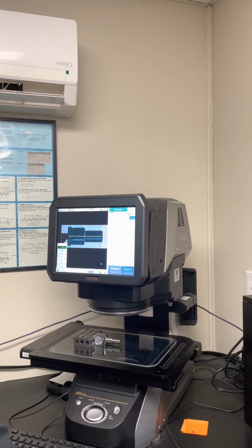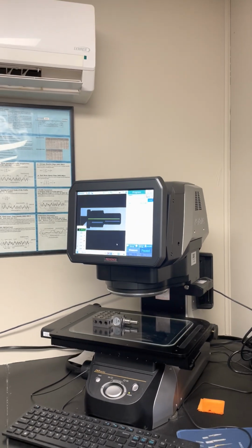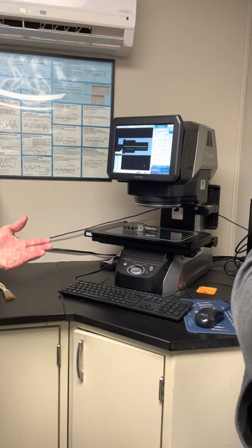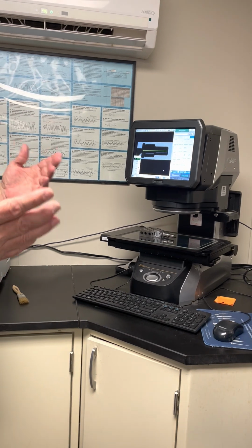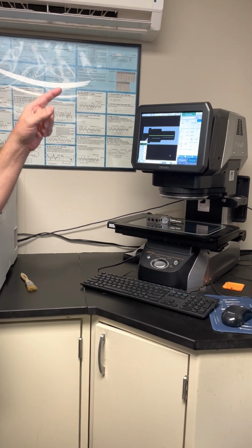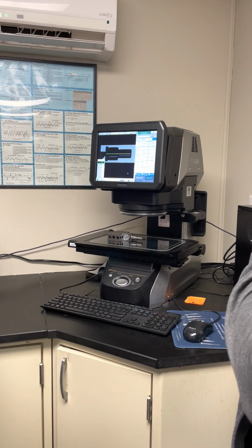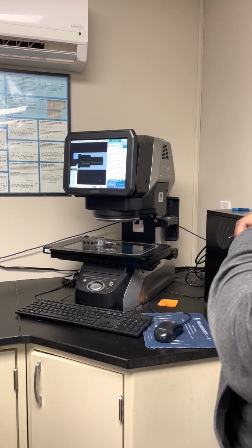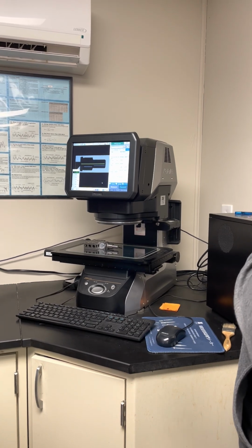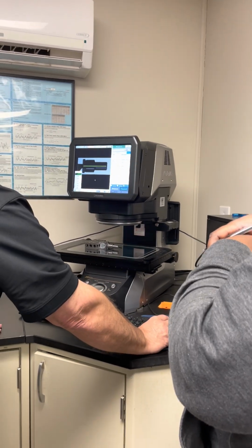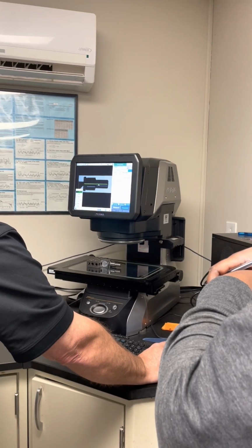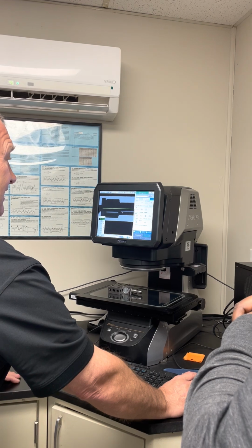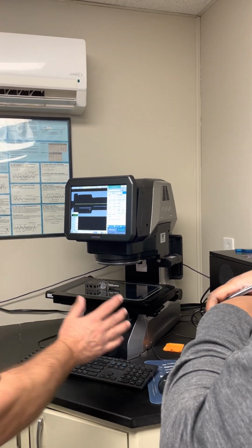Now, we have to remember that when we're creating lines or points or circles, let's say I create a line, I'm taking 2 points, correct? But I'm not really taking 2 points. I'm taking 2 points to create a search window. Within that search window, I'm actually going to collect up to 50,000 points per inch. So I want to take a quick look at this center line to see what points we're creating, just to make sure that I'm not reading the noise.